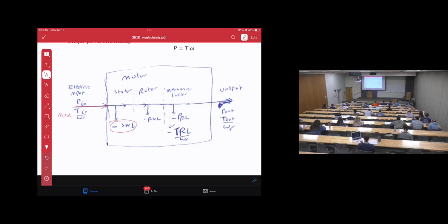After that, the power flow will go to the rotor. Then there will be rotor winding losses. Now we are done with the electrical parts. The motor starts rotating. Then we are in the mechanical parts. Then there will be subtraction of the rotational losses. After that, it will be the output, which is P out. So the development power is located here, P dev, before the rotational losses. Output power is located here. Input power is located here.